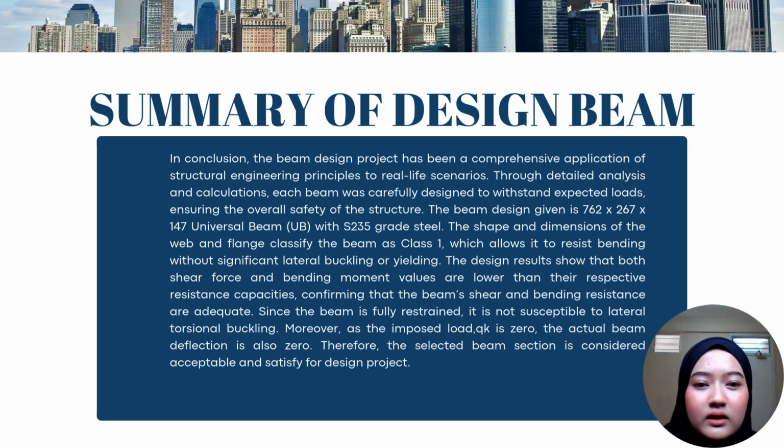The beam design given is a 762 x 267 x 147 universal beam, UB, with S235 grade steel. The shape and dimensions of the web and flange classify the beam as Class 1, which allows it to resist bending without significant lateral buckling or yielding.